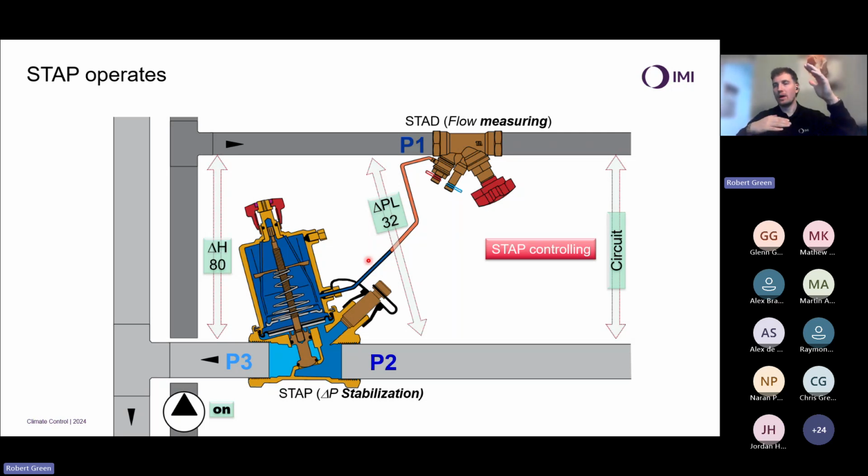So there is also always a proportional working band. Depending on the design of the valve, it can be anywhere from about plus or minus 20% of differential pressure up to about plus or minus 50 or 60%, depending on the type and design of the valve. But in essence, in this example, we're only getting 10-ish% difference maximum under an increasing differential pressure.